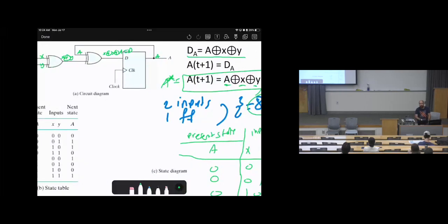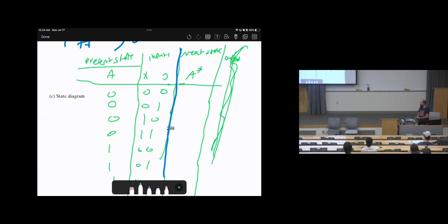So here is the easy part. The difficult part is converting exclusive OR into its equations, which is X Y bar plus X bar Y. Then you need to apply this with the A. This will take so long, take a lot of effort, and the chance of getting mistakes will be high. So sometimes when you see these kinds of questions in the exam or in the quizzes, using the nice feature as a shortcut, you can solve this question within 5 minutes, or you can spend 20 minutes and you will get a lot of mistakes. So we don't need to convert this to equations. We can use the nice feature.